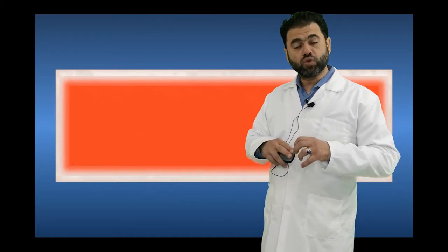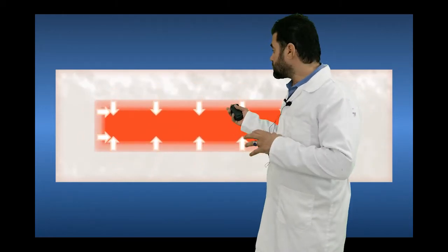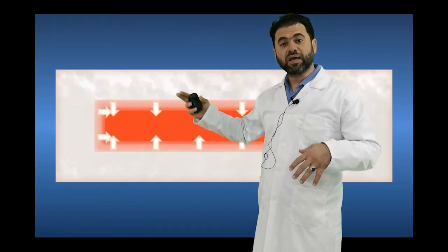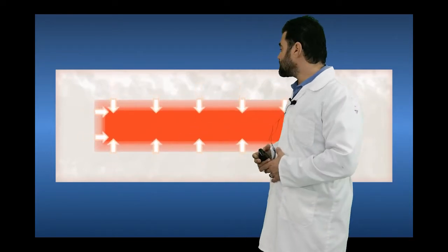Then this will make the outer surface of the ceramic solidify, and the internal structure is still in a molten state. Okay, and now when it starts cooling, this molten inside will get cold and shrink, and when it shrinks, it will start pulling the outer surface to the inside, and this will create a compressive strength within the ceramic, the outer layer. So if there is any crack, it will pull it all together and it will try to close these cracks.